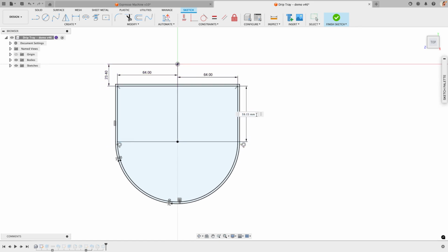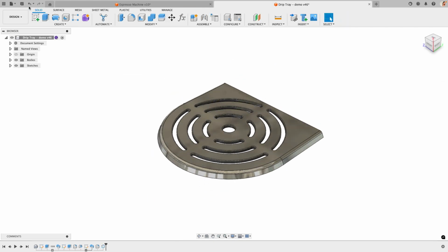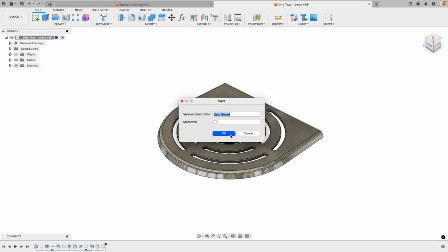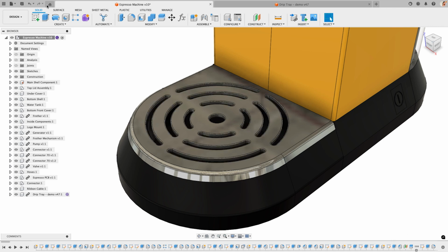And I'm then going to go and minus 4mm from that result, making this slightly shorter. We'll save the design, pop back to the top level, do an update. Our changes come through, our clash is cleared, and our design work is done.